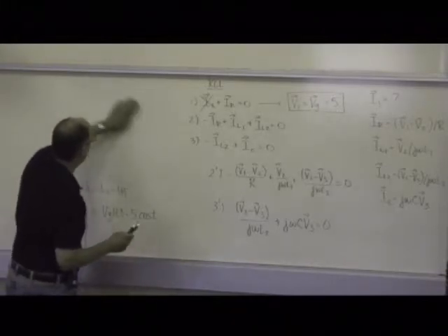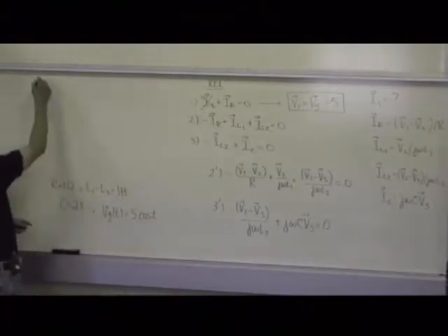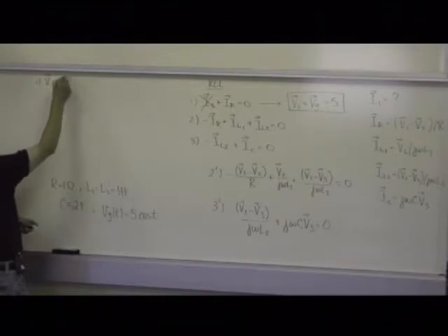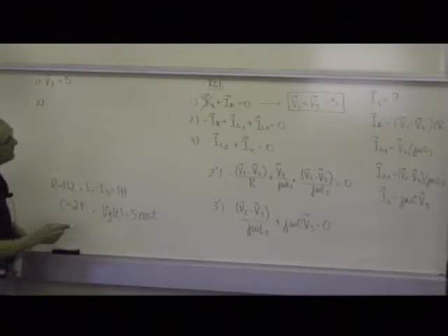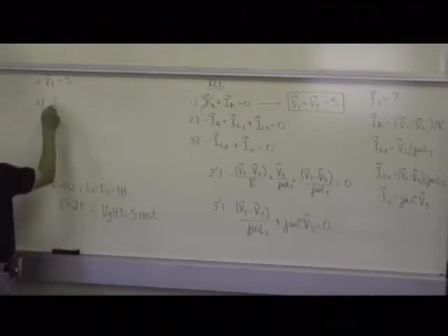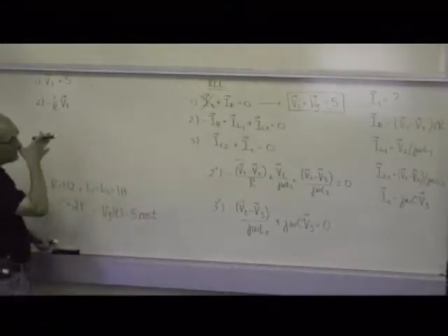Sort these equations out. First one is trivial, just V1 equals 5. Second one, next to V1, there's only one term, minus 1 over R. It's a good idea to sometimes put a little half a bracket to make sure that you don't skip any terms.